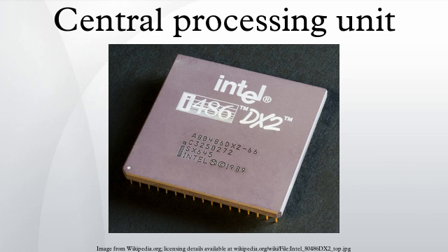Another major issue is that as clock rates increase dramatically, so does the amount of heat dissipated by the CPU. The constantly changing clock causes many components to switch regardless of whether they are being used at that time. In general, a component that is switching uses more energy than an element in a static state. Therefore, as clock rate increases, so does energy consumption, causing the CPU to require more heat dissipation in the form of CPU cooling solutions.